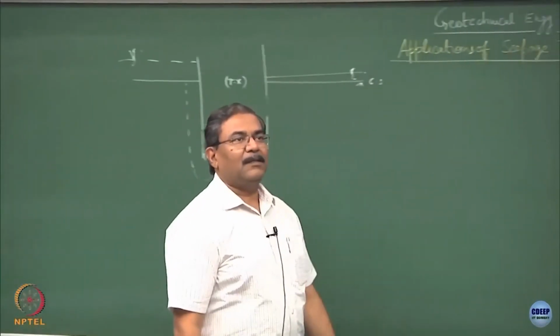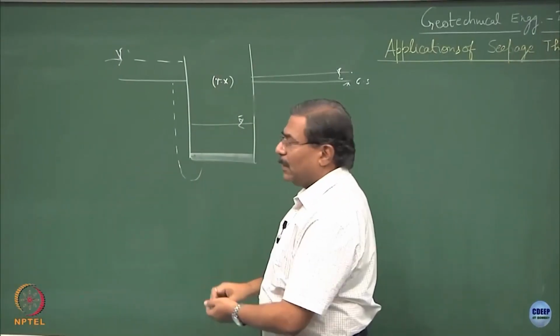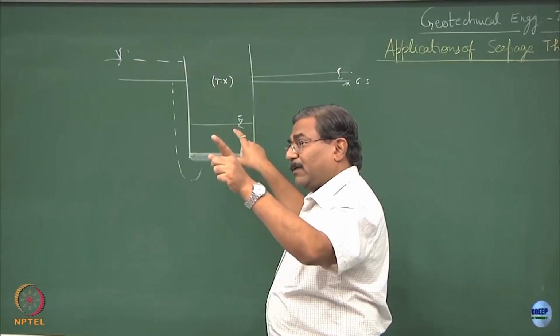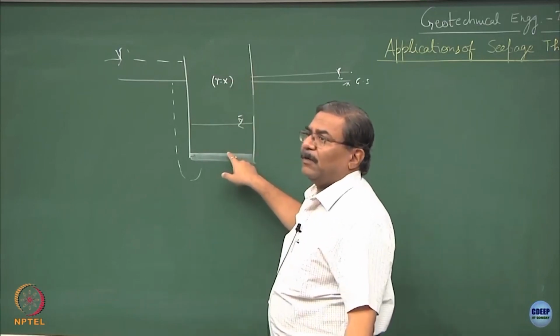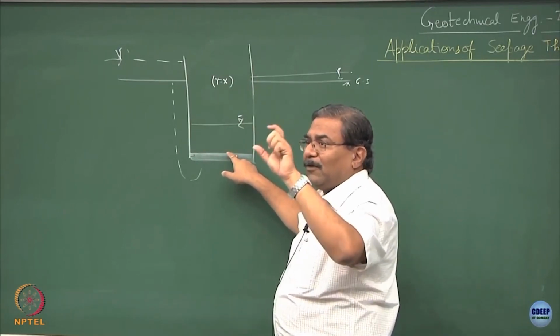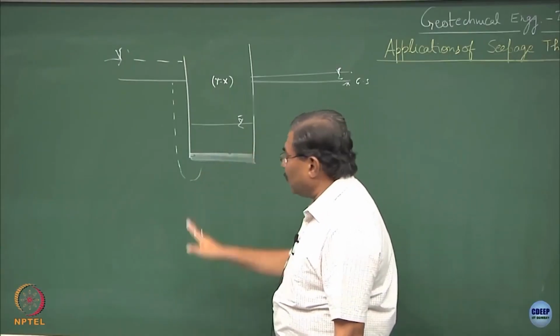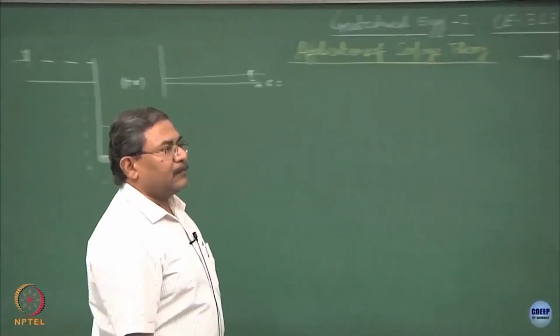How to stop this? Design a raft, overload the system, create the space. I am getting the advantage of 25 kilonewton per meter cube of concrete, RCC, clear? And this was how much? 15-16 kilonewton per meter cube. So, that 9 kilonewton per meter cube multiplied by the thickness of this is going to be the added stress on the exit gradients, mechanics done. Is this okay?